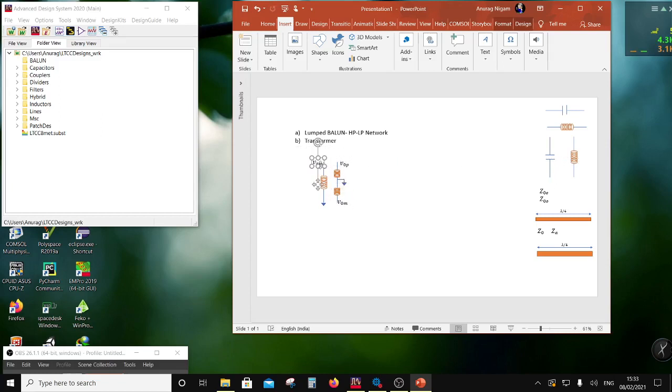Now this is a form of a coil. This is based on magnetic coupling, right? So that's how a transformer works. If you want to make a BALUN which is transformer based on a chip, you will make basically three coils, and these three coils will interleave in such a way that there is sufficient coupling between them, right?